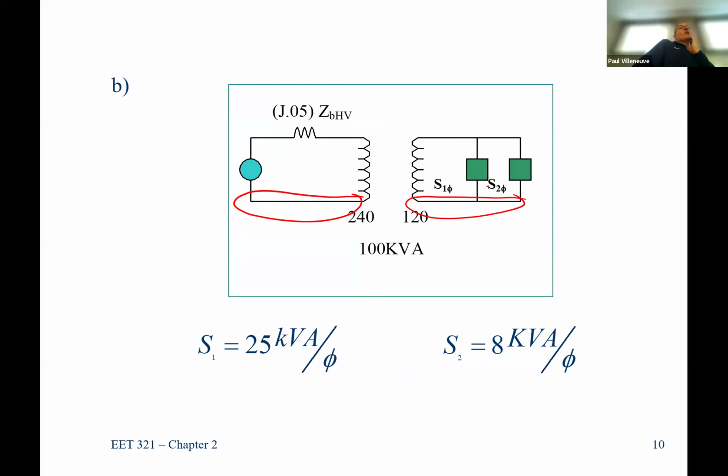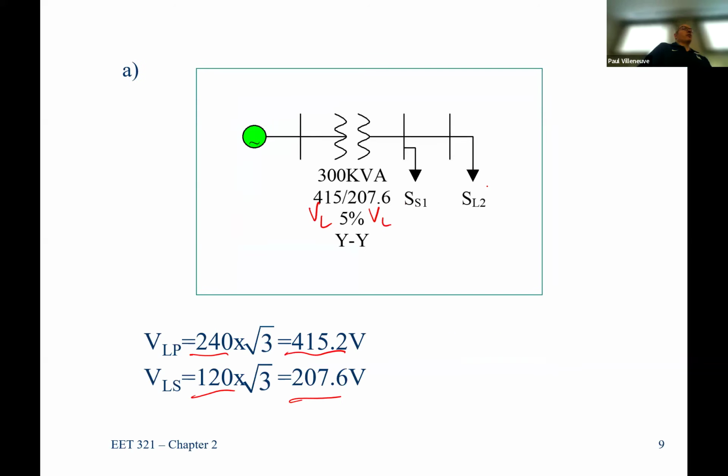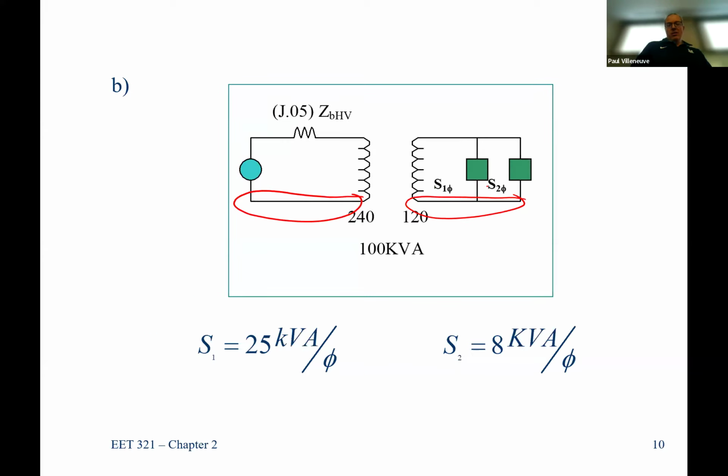It's trying to indicate the neutral, isn't it? But the neutral doesn't often run, so you don't necessarily have that neutral connection. So a single line diagram is almost always shown like this. Very rare that you'll show a circuit diagram like this. This is if you wanted to analyze a circuit to figure out what's happening, but in reality, you would not show this in a field drawing.